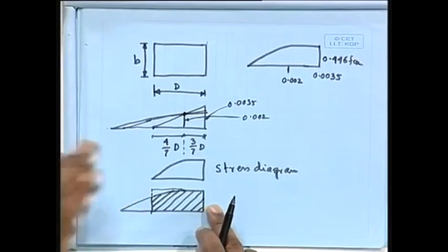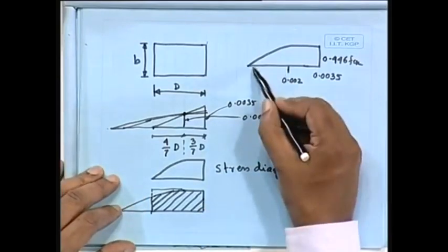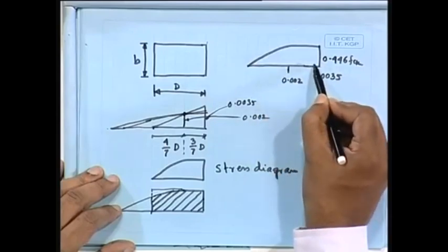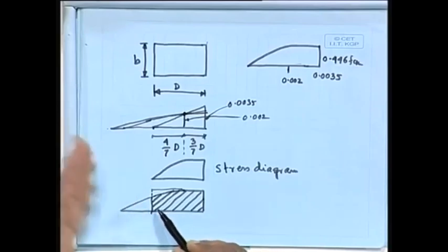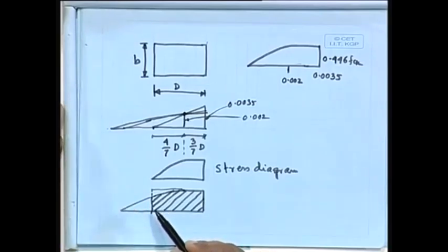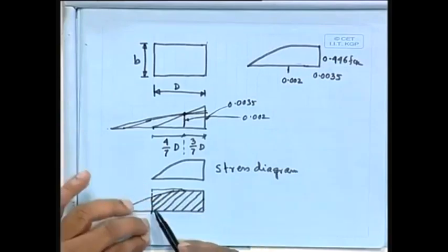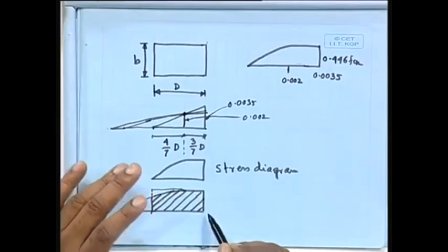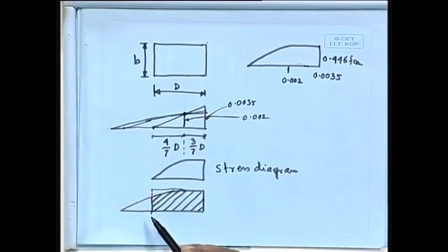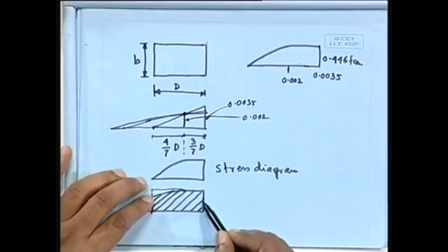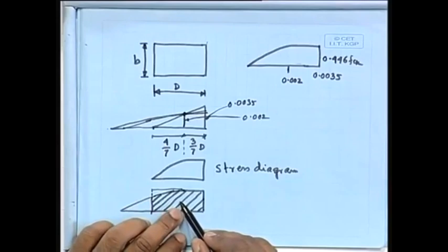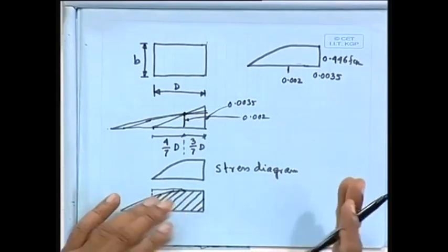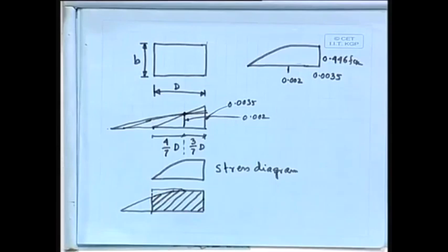Compared to your beam problem, there is no problem because we are taking the whole area, but whenever you are talking about a column, in most of the cases it will happen that it is partially loaded, that is, the stress block will not get the full one, we shall get only part because the neutral axis is outside the section, and this area we have to calculate. So what is our objective here? Our objective here, that P and M we do not know, because since it is P and M there are two parameters, so we do not know in which case it is safe.